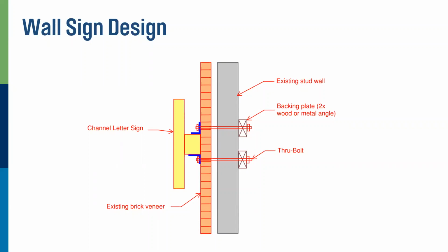Sometimes you'll do powder coated steel or something like that, but a lot of times it's aluminum. The problem with bare aluminum and steel is galvanic corrosion. The aluminum will rust. It'll start pitting out.